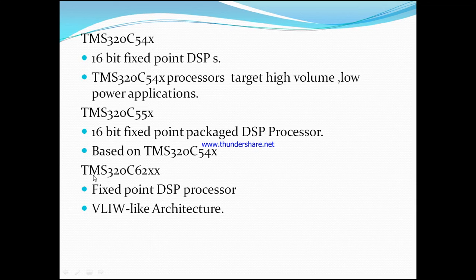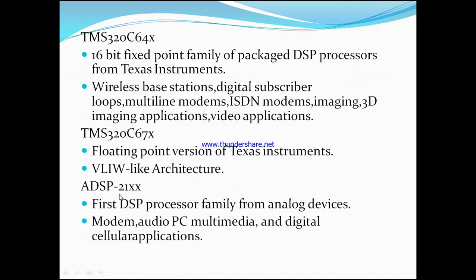And the TMS320C62XX is another fixed point DSP processor from Texas Instruments. It is also based on VLIW architecture. The next one, TMS320C64X, is a 16-bit fixed point family of packaged DSP processors from Texas Instruments.